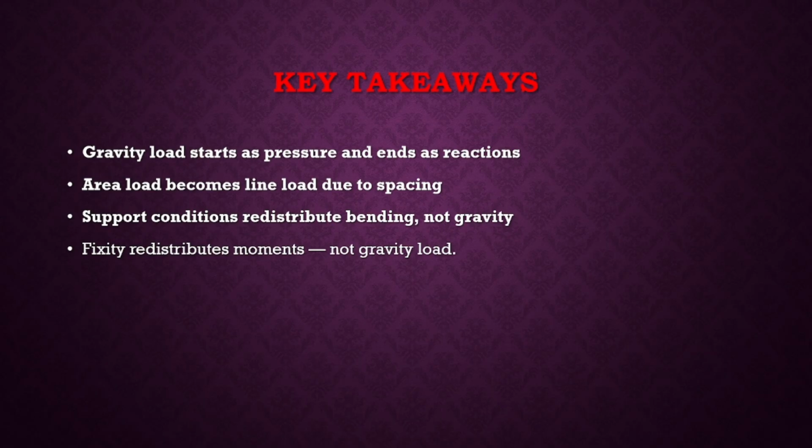The reaction remains same because of the support. Whether you have a pin connection or a fixed connection, the reaction will be same. Only thing that will change is the bending behavior. Because of fixed support, there is redistribution of moment. In case of simply support condition, the bending moment is 0 at the support, but in case of fixed support, you have certain bending moment at the supports. If you understand these 3 points clearly, you understand how gravity load really travels in a structure.